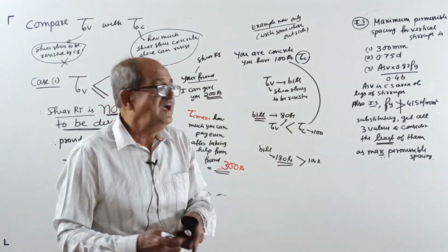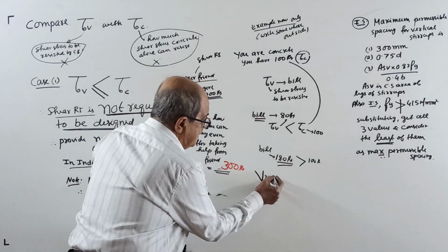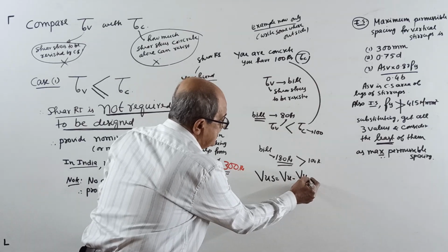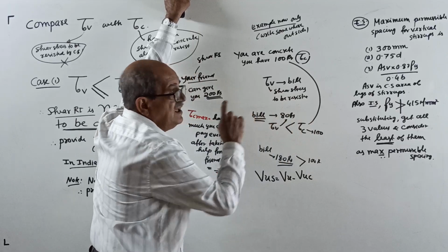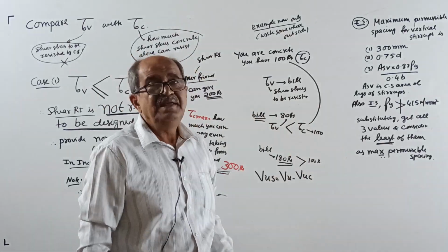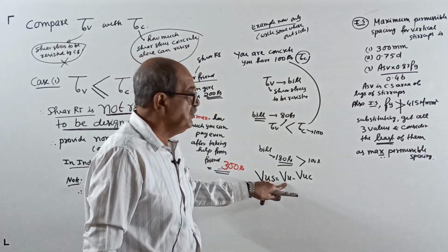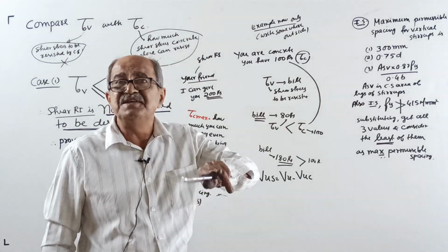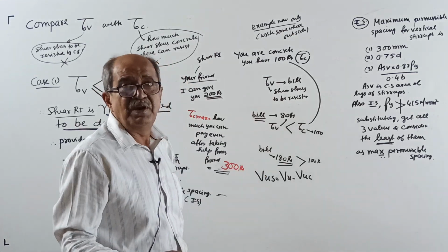That's why later we will write shear force to be resisted by stirrup equals shear force Vu minus shear strength of concrete. See, 180 rupees, subtract how much money you have got. From 180, subtract 100. 80 rupees, you take help from your friend. Here, from the shear force, subtract how much shear force concrete alone can resist. Balance, you provide steel. Okay, now, hope everything is clear.